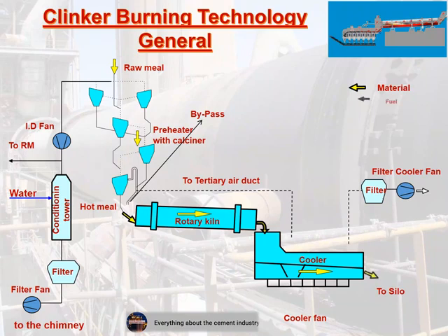B. Fuel. The raw material is heated at 2 points. 1. The main burner, from the outlet of the rotary kiln. 2. Calciner in preheating tower. C. Gas and fresh air. For the clinker cooling process, fresh air is pumped into the cooler through a set of cooler fans.